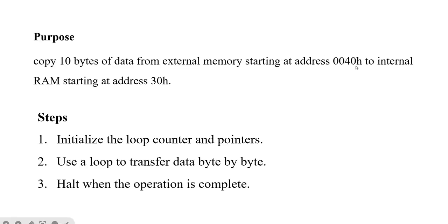So here I have written 0040H. This is for the external memory location. Here this is a 16-bit addressing for the external memory, and the 8051 microcontroller uses a 16-bit address for accessing external memory. So a 16-bit address will allow the microcontroller to access a memory range from 0000H to FFFFH.